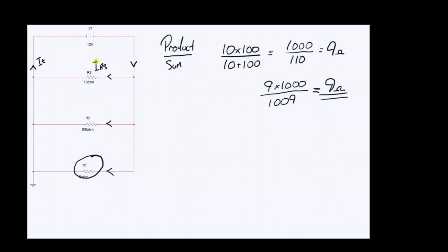For a parallel circuit using exactly the same resistors as we did in series, the current flowing through the circuit, the total current, is much greater. Therefore the power will be much greater. We can work out power now. Total power dissipated is equal to V times I, 12 times 1.332, which is roughly speaking going to be around about 16 watts. Much more power for a parallel circuit.